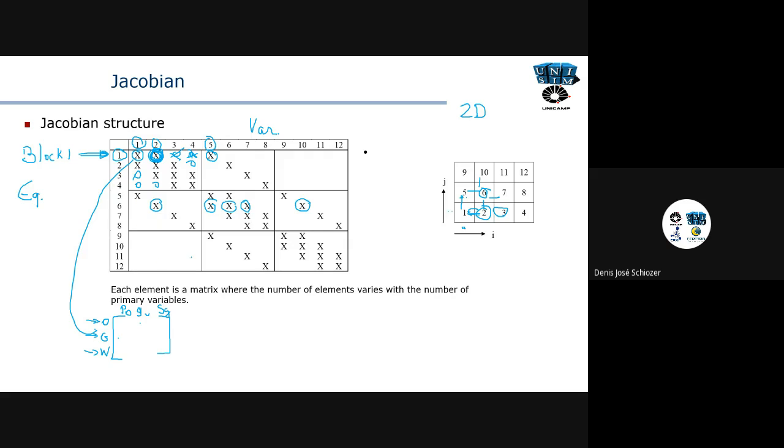But if I know that there are a lot of zeros in advance, and if I know that the zeros are here and here and here, for example, all these parts, there are special ways to solve this matrix much faster, considering that I know that these matrices have 5 diagonals, okay? And this is one of the advantages of the Cartesian grid, because in the Cartesian grid, I know in advance that I'm going to have this simple matrix to solve. So not only do we know that we have this number of neighbors, but also we know the type of matrix we're going to solve, so we can use simple methods to solve for this iterative procedure, okay?